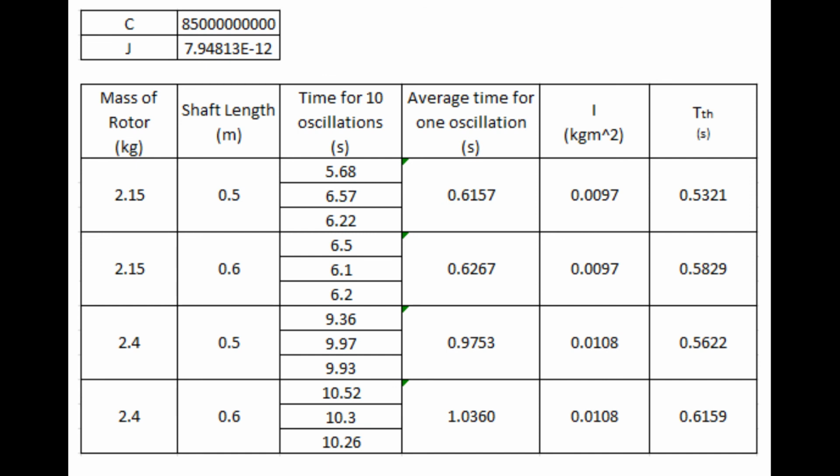Again, shaft length is one of the components which play a role, because if we had more length of shaft, we could have got better results. And the last one, which is the main, is human error, because it always plays a major role in measurement of the readings. So that's how we can determine the frequency for a single rotor system.